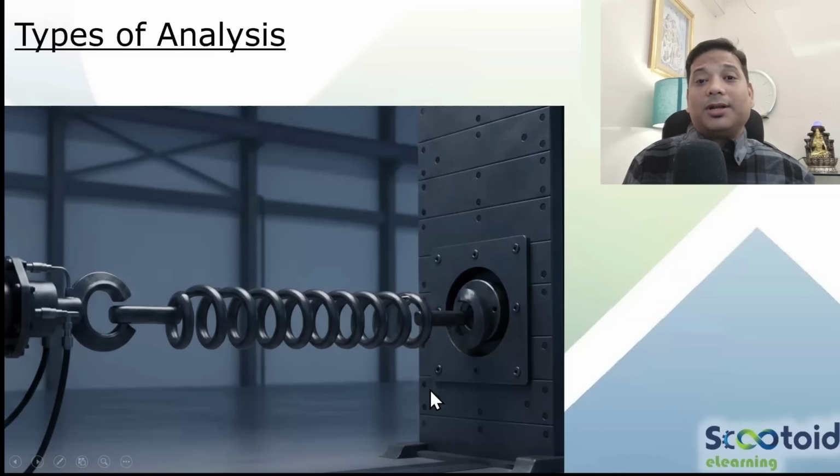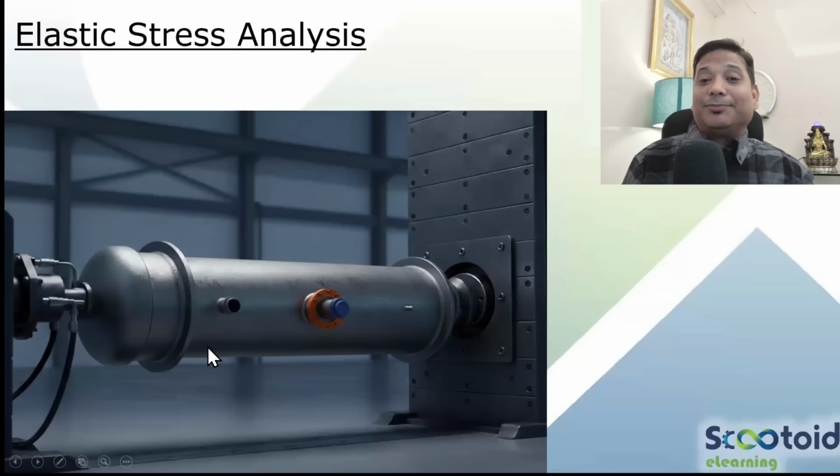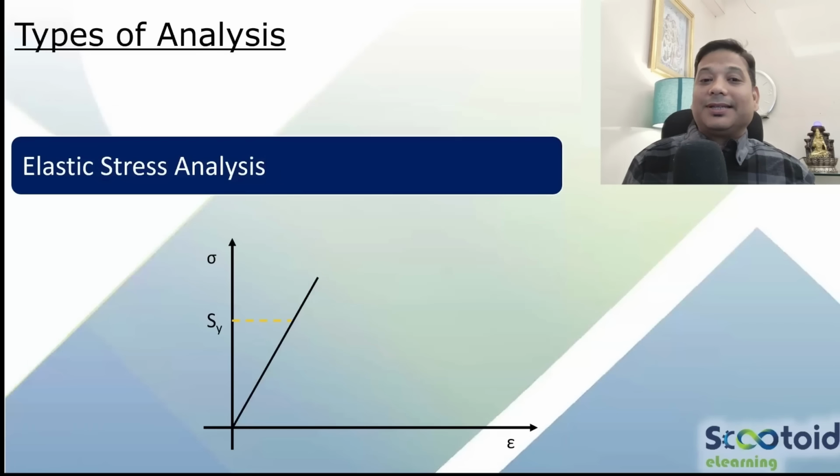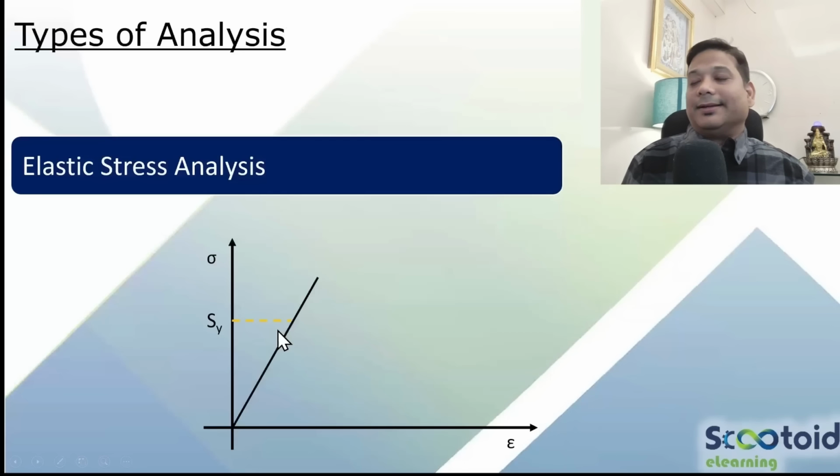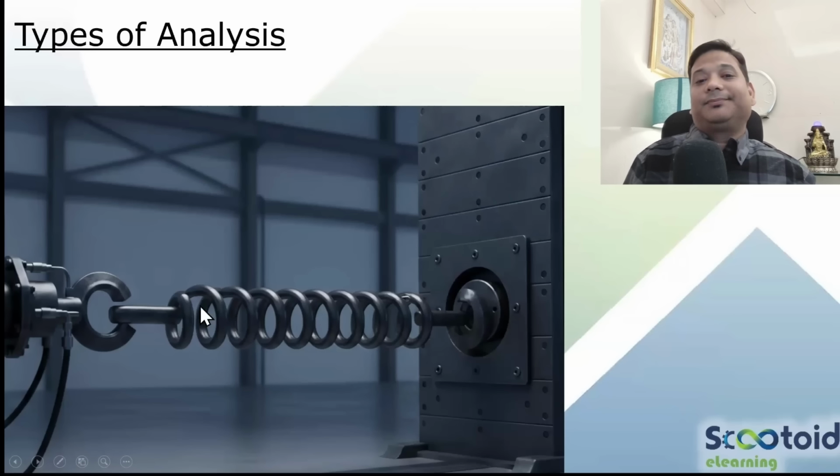Same way, your model, the pressure vessel model, if I simulate it in a similar manner, if you keep on stretching it, try to imagine a simple tensile bar instead of the spring. What will be the kind of stresses in that? If my vessel is not a complicated shape, it is just a round bar, and if I apply a load on that, what kind of stresses will be there? Axial tensile. Now, if you think in terms of primary membrane, primary bending, local, secondary, tensile is the nature.